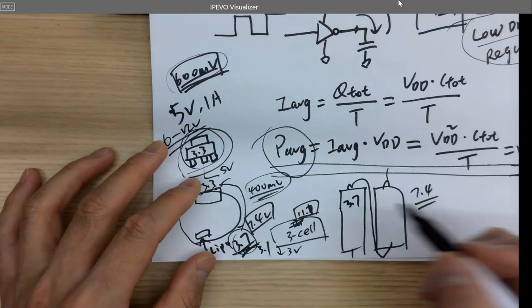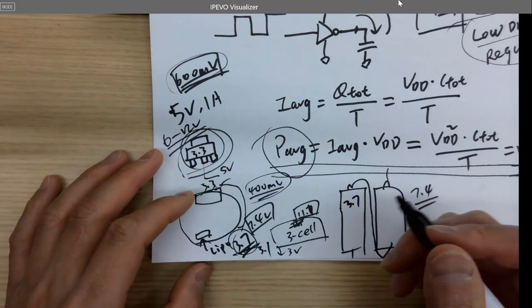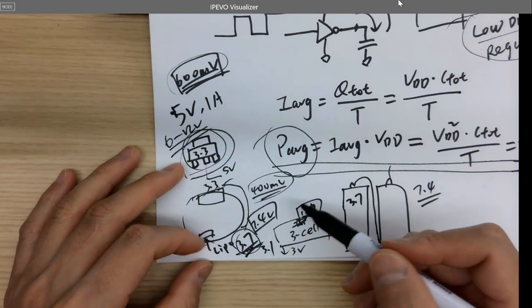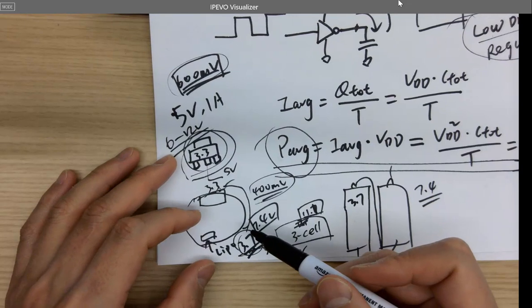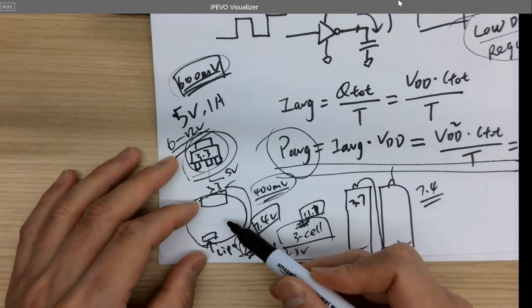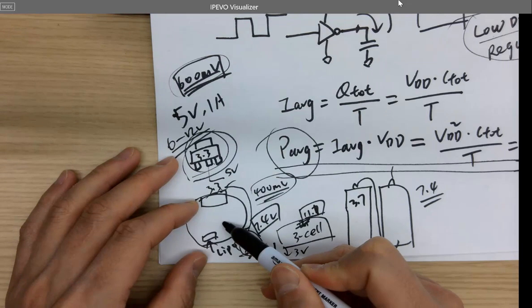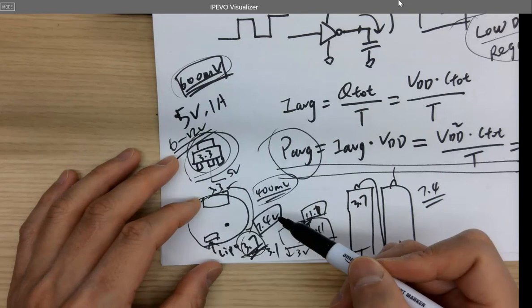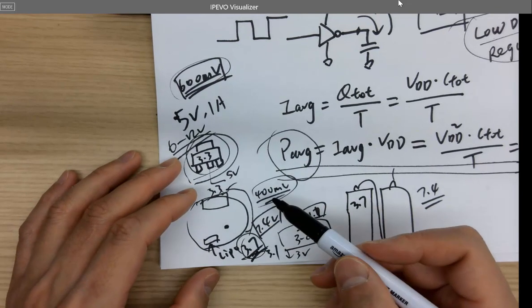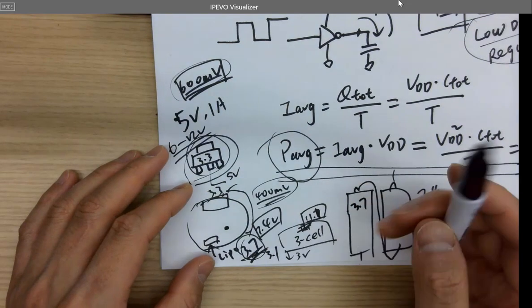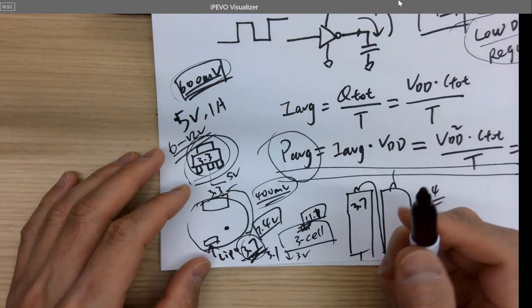Okay, so you have to pick a high quality regulator. So I was able to find that one. If you go back to the tutorial in that class, it's a super tiny chip. It's probably the same size as this little mark on the paper. And very difficult to solder on the board, but it works really, really well. I think the dropout voltage is only like 200 or 100 millivolts, which is amazing, like only 0.2 volt loss.